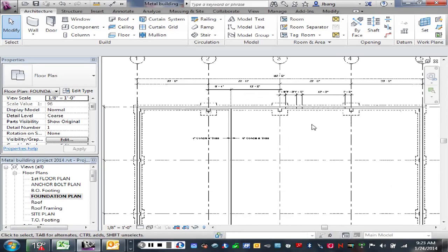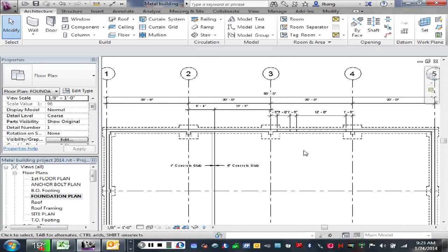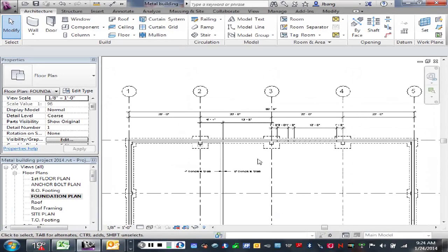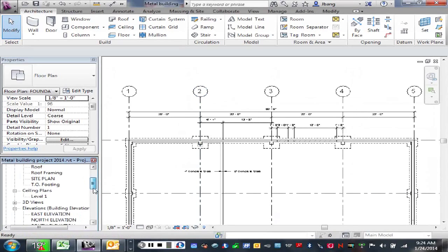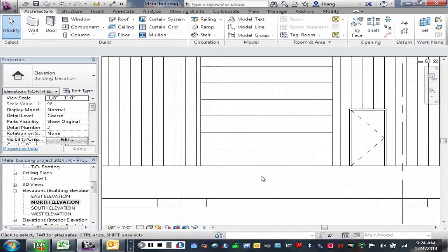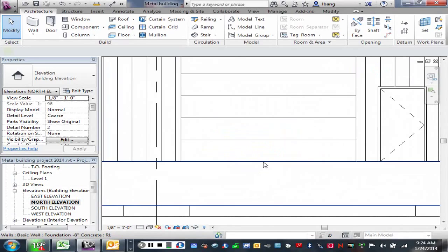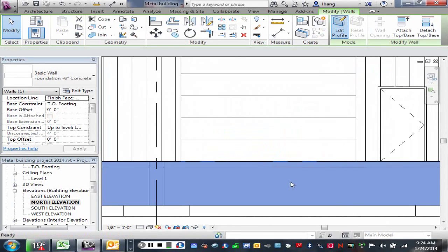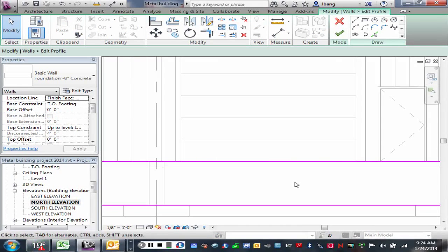Okay. So if we want to edit the wall, we just have to go to maybe an elevation view. At this point, I haven't. At this point, I just put a hatch there, right? And theoretically, would I even have to change that? No. But if I wanted to, and I'm not necessarily recommending that we do this, I could go to, say, the north elevation and look at this, I could click on this foundation wall and edit the profile of it, right? And drop down different sections of that wall. You've probably done that in the past. In this case, I'll just do one here.